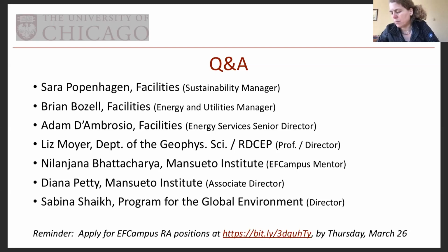The other thing that you have to be careful about when you look at those numbers is whether they're what they call source EUI. Energy use intensity, EUI, is the number, and there's a source and a site version of the same number. So the site EUI just takes all the electricity in these units of watts of electricity and adds them together with your natural gas usage in terms of watts of primary power in the natural gas. But that is completely unfair because it makes your electricity look like it's not a particularly high energy user, because you're not accounting for the fact that you needed 3 times as much primary power to make the electricity in the first place. Do you buy that?